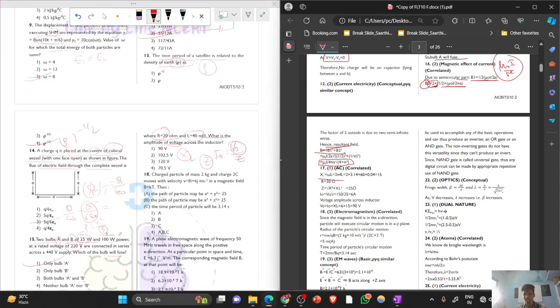So from here you can get the peak voltage. Now looking at the solution, you get XL, you get R, and from here you can get Z, which is under root R square plus XL square. From here you get the current, and peak voltage is I naught into XL. Amplitude across the, okay, oh sorry, it is asking about peak voltage, so from here you get this value. Okay, along the inductor, you just need to understand XL and I naught. This will be your answer. After solving, it gets 90 volts. Now moving ahead.